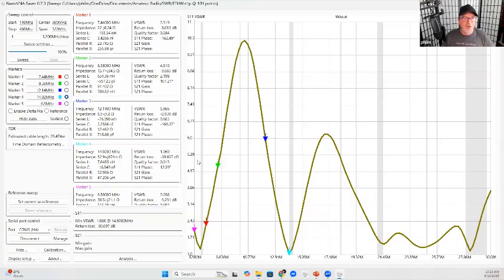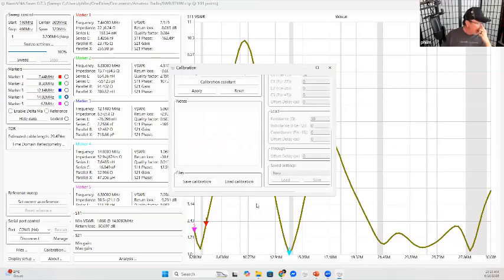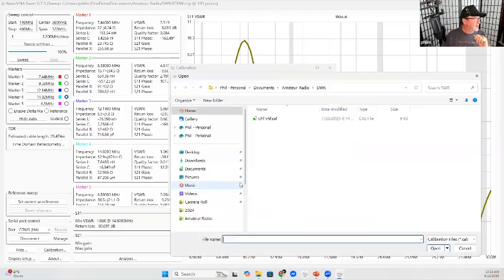Yeah, I have. This is what I was taught, and this is where the experts can come in: you calibrate it once for each frequency range. So if you remember, when we went into calibration, we calibrated it for 140 to 460, so I could do a tri-band. I saved that calibration. If I wanted to do that again, I could load that calibration, and there's a calibration file that I created back in July. So I can load that, and it's calibrated. So I don't need to go through every step, as long as I stick in the same frequency range.